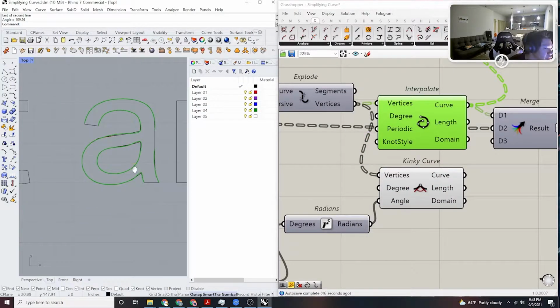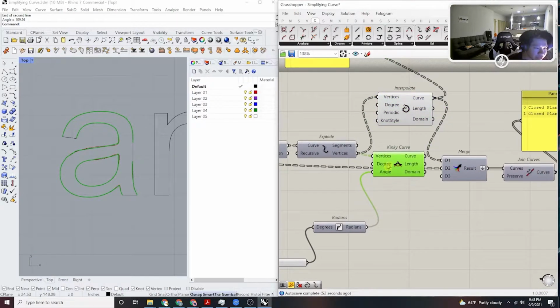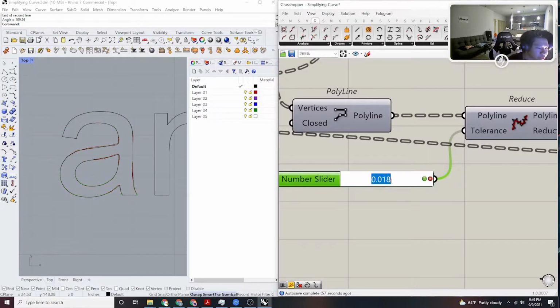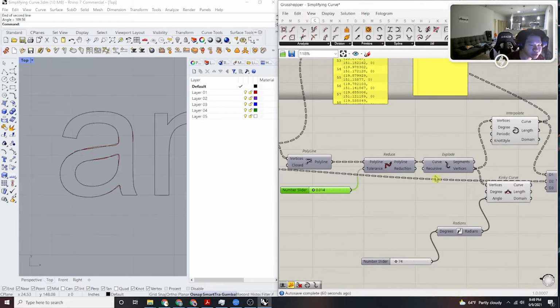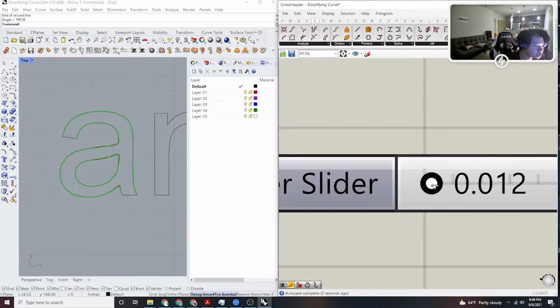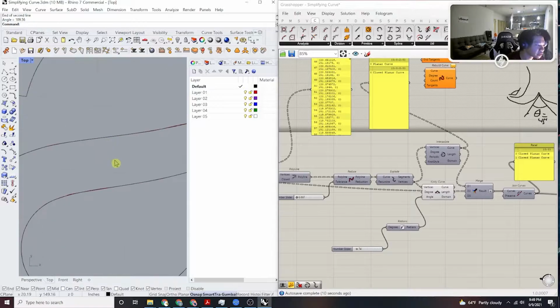but it doesn't look as good as even the interpolated one that I have here. So what you have to do here, well, you don't have to do anything, but what I did here was I took this curve and I just lowered the tolerance by increments. So out to 4, see what that looks like. Okay, didn't really change too much. So let's keep going. Okay, 0.07.